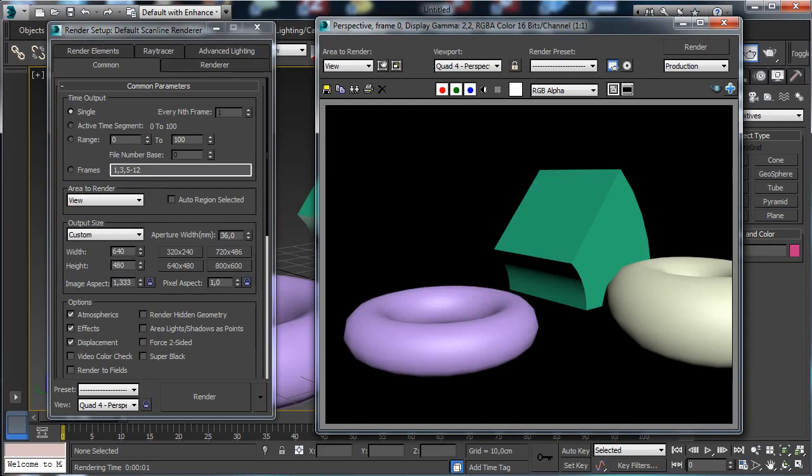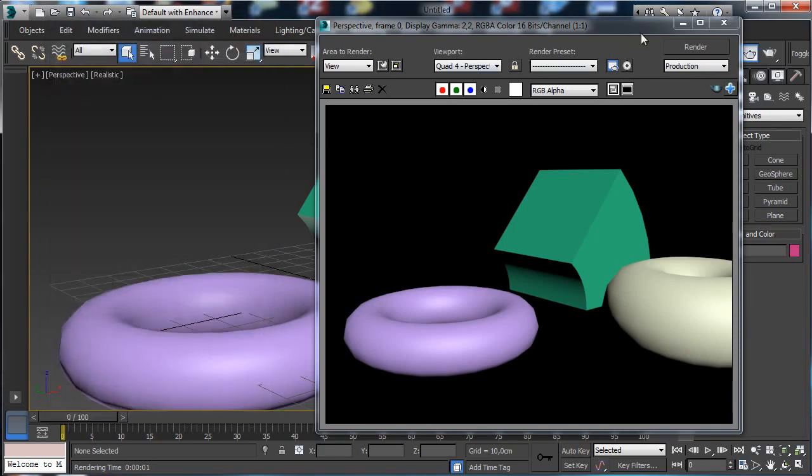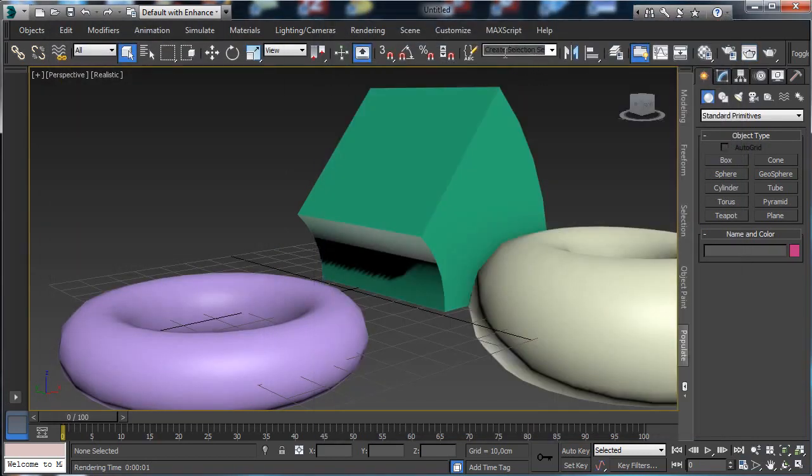But in case you are using, for example, a bitmap with no standard gamma, you have to set the gamma manually. It is important when you, for example, need to work with bump maps or normal maps, where you need to work with a pixel in a more complex way. But in this way there are fewer problems understanding how to manage everything for basic users, because everything is done by 3ds Max by default.